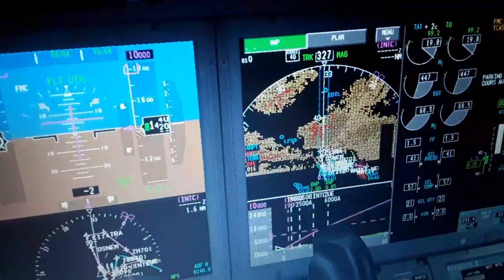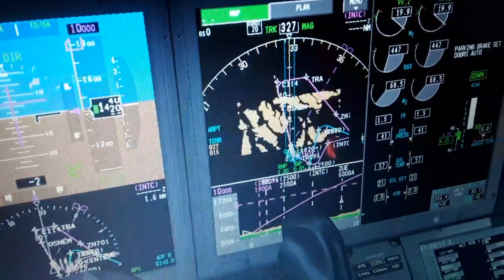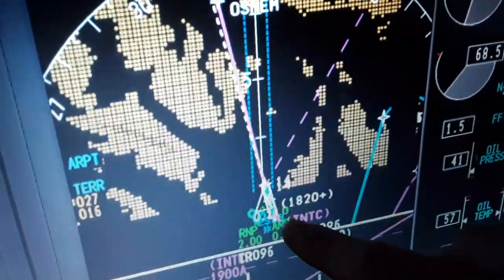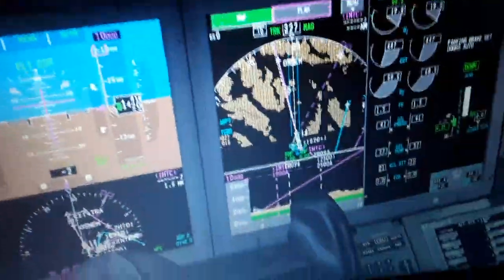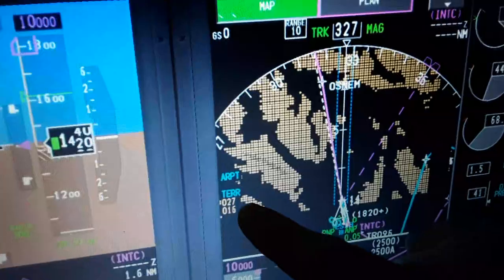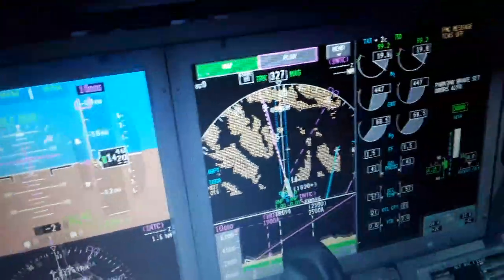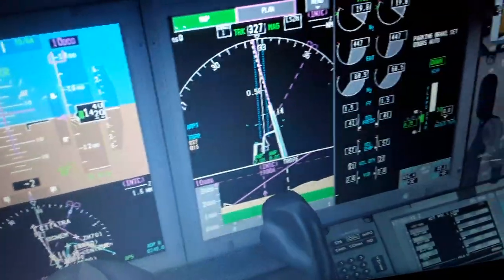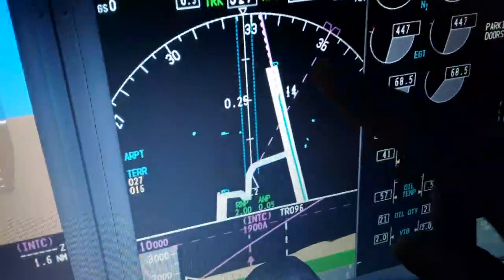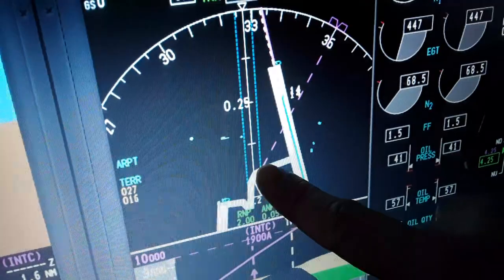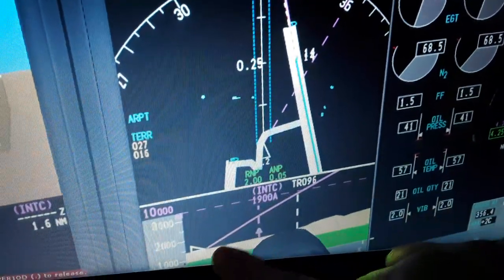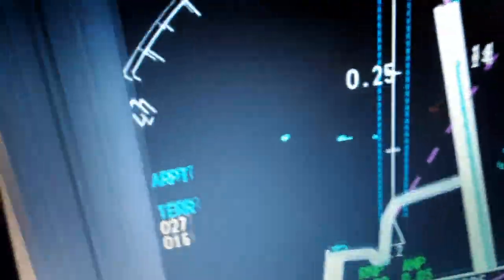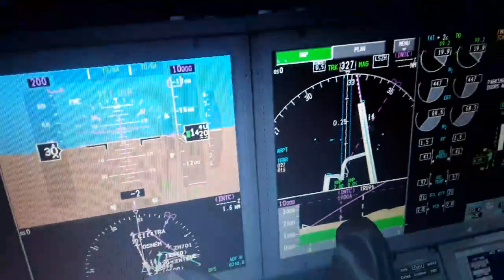So we have, again, if you look closer here, you can see the runway we're gonna use for takeoff. We have on the right side the elevation of the terrain also. For this range, 2,700, for instance 1,600. So as we look closer and closer, you will see we have the runway here displayed for takeoff, the taxiway in front of us, the other runway, and the terrain, some mountains with yellow, green or red. The terrain elevation right now is 2,700 for this distance.